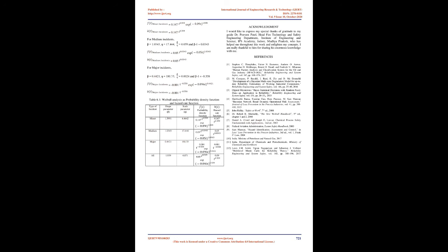6. Conclusion. From the above calculations and research it can be concluded that the data of incident occurrences based in an oil refinery, including minor, medium, major, serious, and catastrophic, help in the system safety assessment in any organization. The system safety assessment has been conducted on the collected incidents data in an oil refinery where rank regression analysis and least square parameter estimation have been performed on developing procedure for estimating the time between occurrences. Weibull distribution theory helped to further document the statistics of duration between the occurrence and reoccurrence of any particular type of incident. This research work provides algorithm evaluation using Weibull distribution for development of probability density function and hazard rate function based on incident occurrences. Now put the values of β and η for all the incidents calculated above accordingly to get the Weibull probability density function and Weibull hazard function.